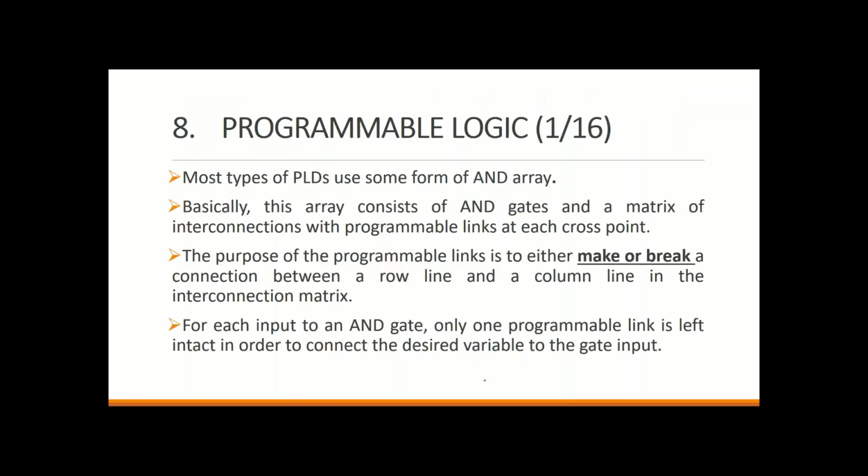Alright. The last part is a bit more of theory, but it's important for you to understand and learn it. Now we have something we call programmable logic. We explained the concept of PLDs, or programmable logic devices, and we said that we can create them with an AND array. In this array, we can create some connections to program it. In order to program this kind of gate, we need to make or break some fuses or links.